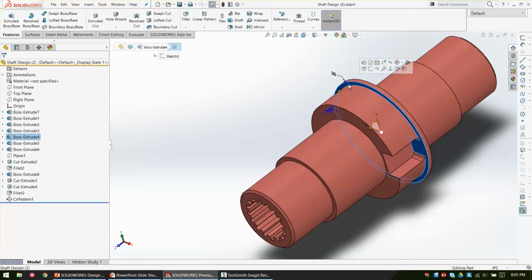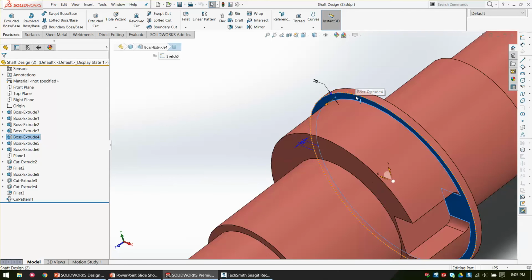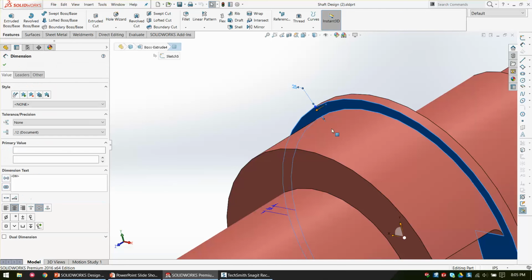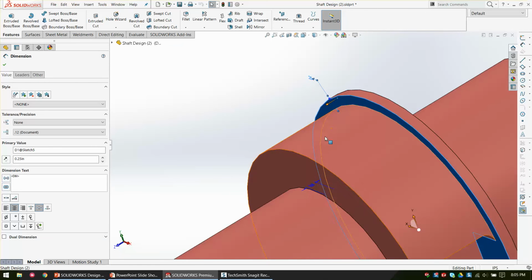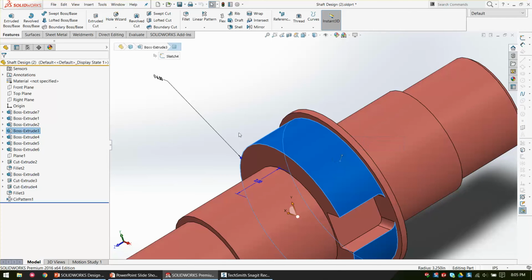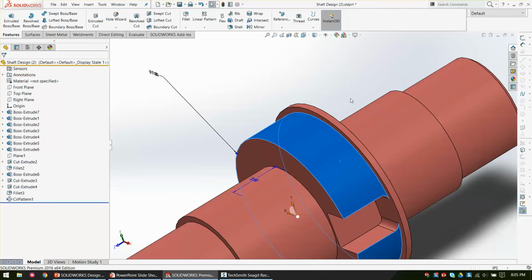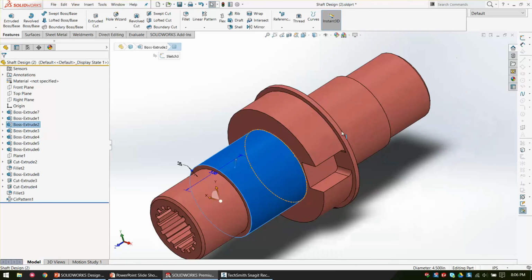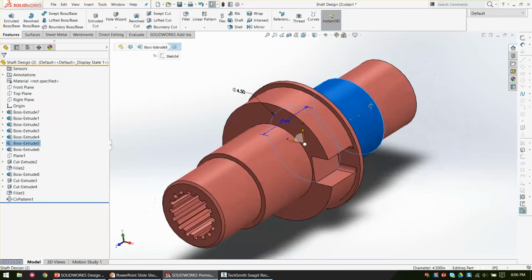So our design intent says we want our retention ring here to always, always, always be a 1/4 inch higher than that. That's our design intent. And even with the layer cakes, you can accomplish this. If this goes to 7, that retention ring grows with it. No problem, we're all on the same page. But then we have other problems with these other retention rings and stuff. And he actually did a pretty good job here.